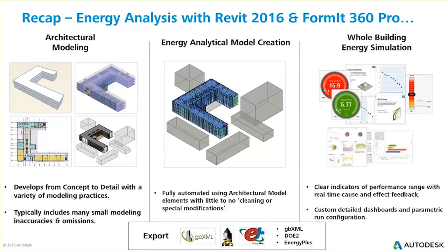I found things that are valuable to find in your physical model, like missing parapets or whatever it might be, things like that. And then finally, the actual nature of the whole building energy simulation itself, we're changing radically as well in terms of we're no longer running a single simulation. We're now running what essentially is equivalent to millions of simulations with, granted, a very small cost in terms of overall accuracy, but perfectly acceptable from the perspective of the directional feedback. It's like less than plus or minus 10%, definitely.